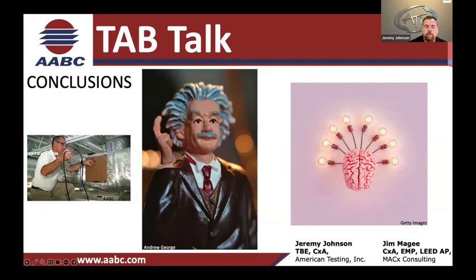That is a consideration. However, in certain massive situations, we did TAB verification on a reheat coil system where the average GPM was 1 GPM per coil. We had 800 devices spread over 5 floors with a combination of manual balancing valves and PIC valves, pressure independent control valves. It took about a week to get the controls guy, because he only had control of about 80% of the valves he could open. The other 20% had to be opened manually.